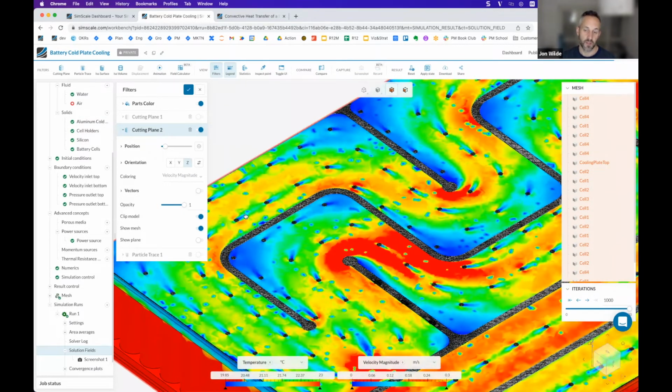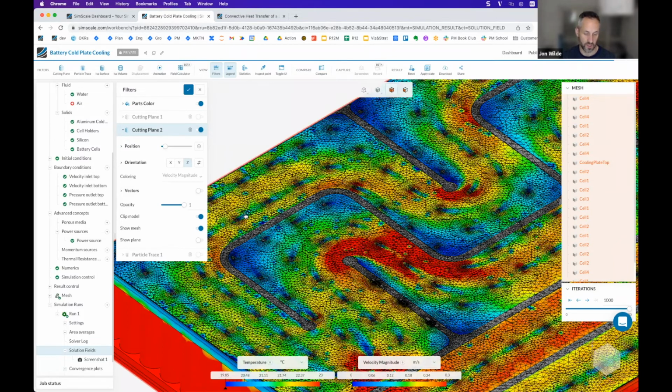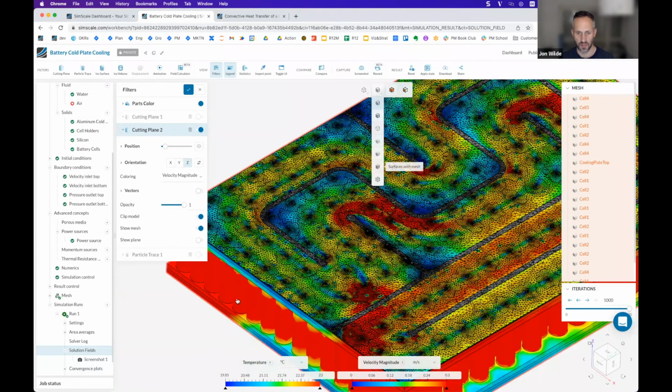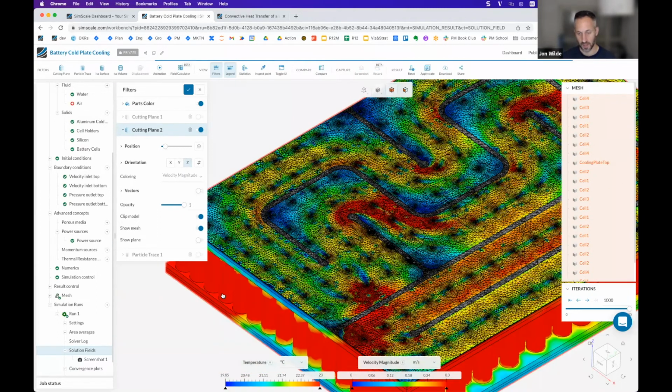We have lattice Boltzmann as well, which is essentially kind of a grid. That's used for fluid a lot. We have immersed boundary as well, which is kind of a blend of the two almost, so that it's not body fitted like this. The mesh here will curve around all of the parts. I can even show it on the cells, so you can see what happens.